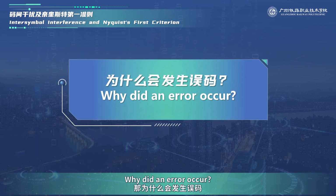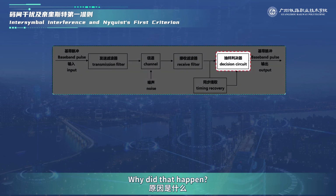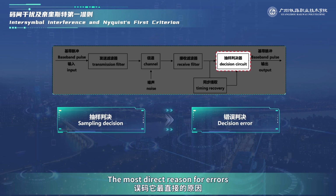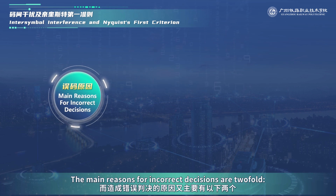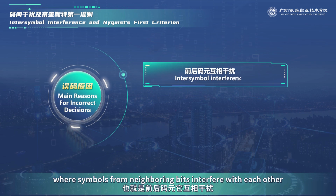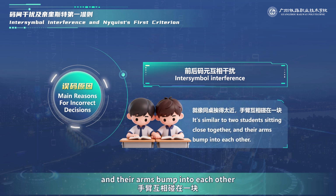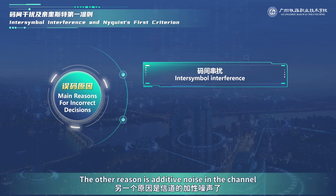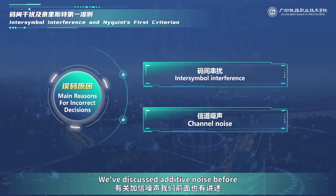Why did an error occur? An error means that the wrong symbol was received. Why did that happen? The most direct reason for errors is incorrect decisions made during sampling. The main reasons for incorrect decisions are twofold. One is intersymbol interference. Is it where symbols from neighboring bits interfere with each other? It's similar to two students sitting close together, and their arms bump into each other. The other reason is additive noise in the channel. We've discussed additive noise before.